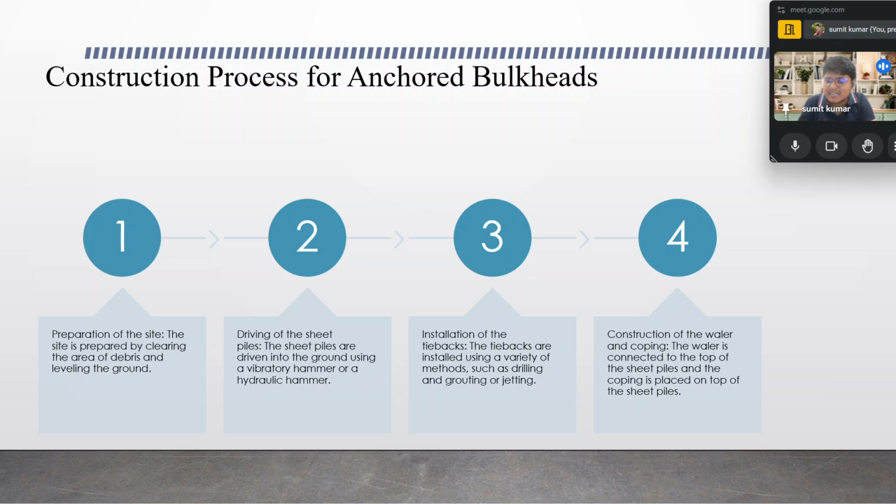As we have gone ahead with this, now drive the sheet piles. The sheet piles are driven into the ground using a vibratory hammer and a hydraulic hammer. One question arose during the previous class, whether the hydraulic hammer is used. I also had a doubt in that class, but the hydraulic hammer is also used to drive down the sheet pile wall.